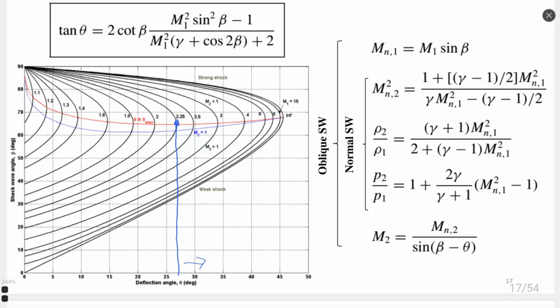So each geometry, or let's say differently, an oblique shockwave should be compatible with geometry and Mach number. Geometry limitation is from 0 to this maximum theta angle, and the Mach number limitation, according to this diagram, is also saying to us, I think I did wrong, this is Mach 2.25, not Mach 2. Mach number also limits the geometry.